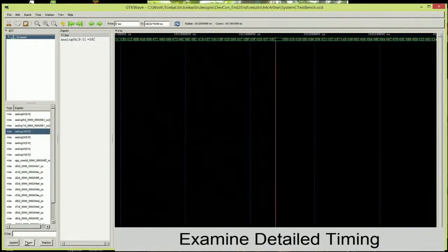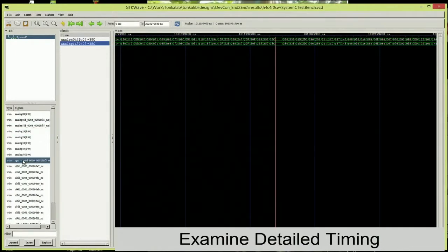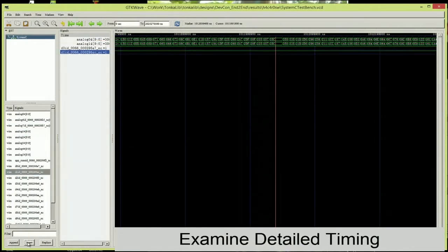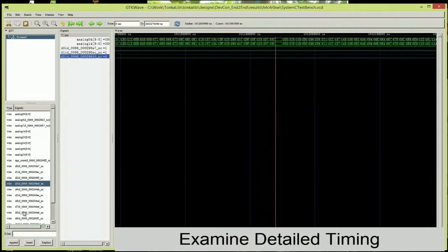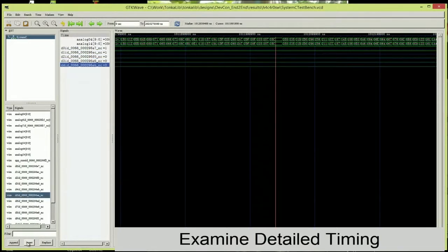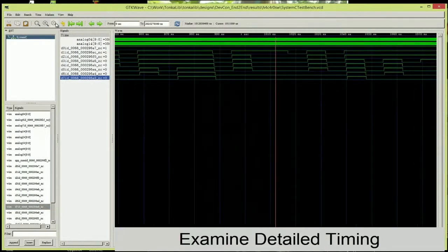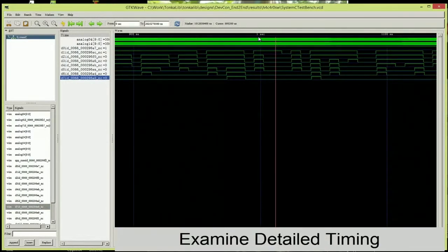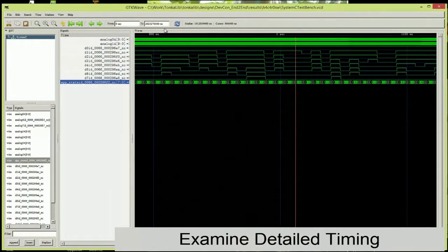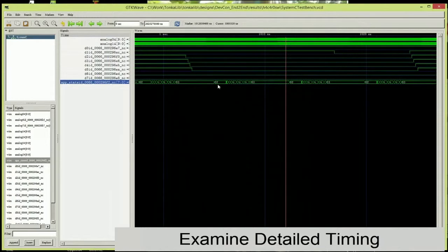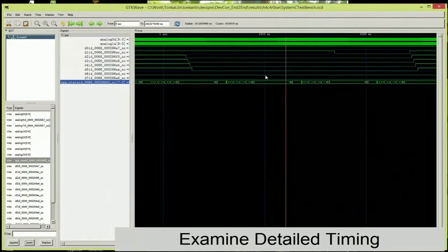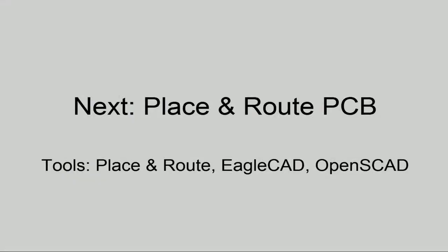I can also take the results of that simulation, which have been logged, and dig down into the circuit. On the top line, I have my analog ports. I'm going through and selecting out all the digital ports on there, and I can see exactly what outputs I generated at what time, do some fine timing measurements, and really do kind of a post-mortem on this. I can also look at the processor state. So if I'm worried about keeping the low power version of the region of the processor, I can optimize my process. So that's kind of the software.